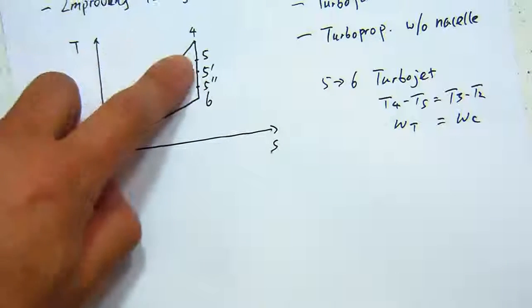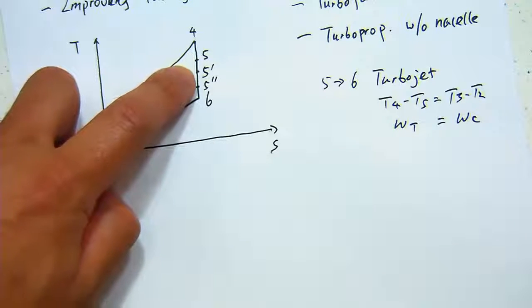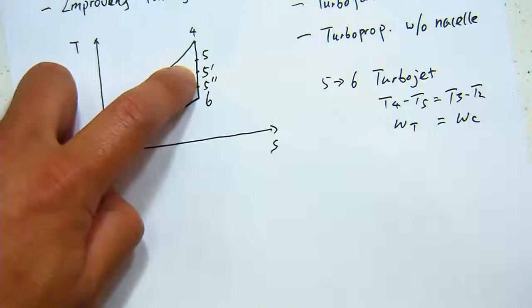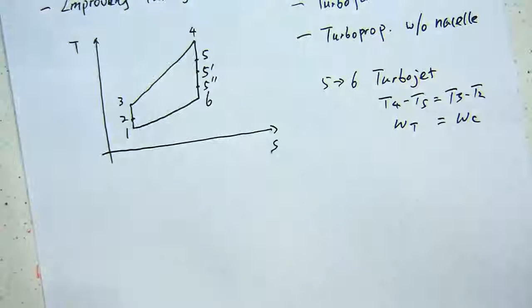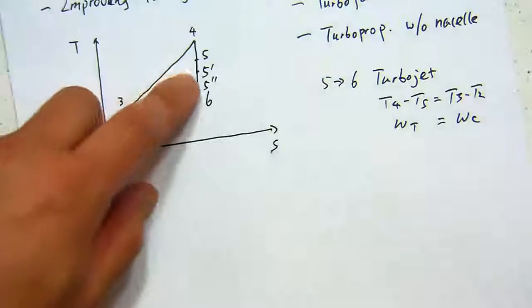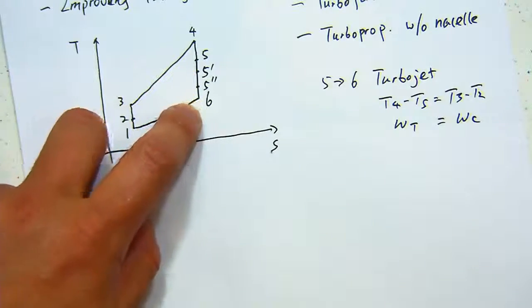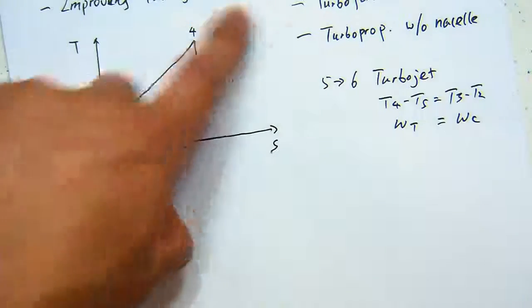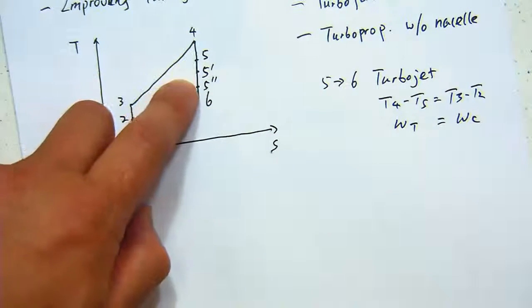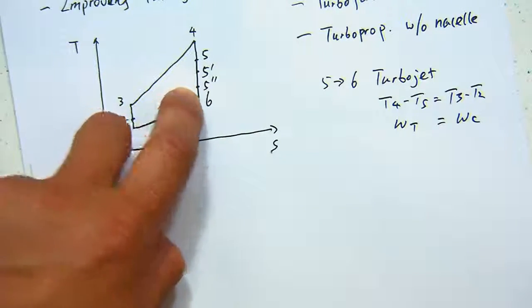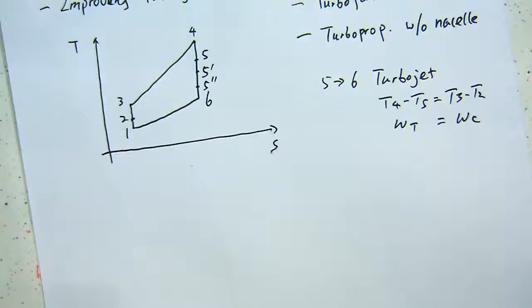if you consider the turbojet is an extreme and the turbofan doing somewhat more turbine work, but still using a large fraction of the energy for the thrust. So that's corresponding to the 5 to 6 step. And the turboprop has an even more turbine work and a smaller amount of kinetic energy as the output.